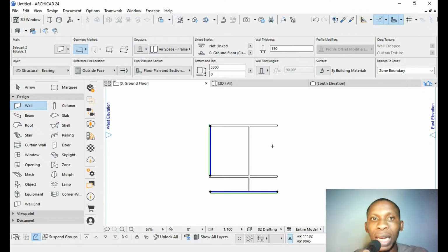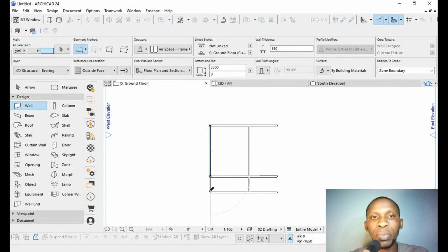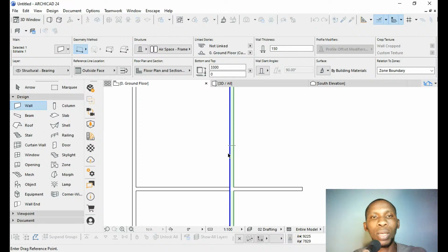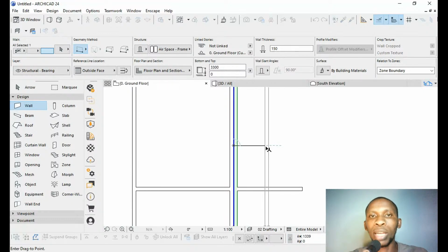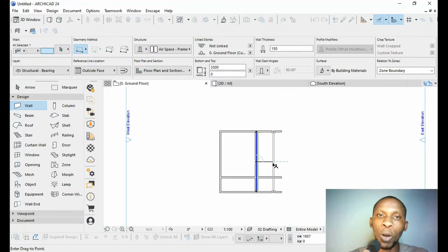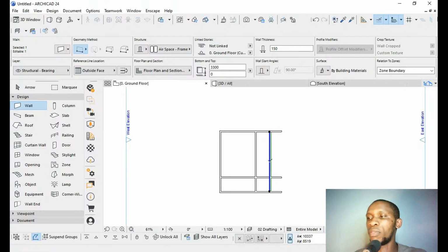The next class we'll be having, right? So I'll drag this down and click together, right? So it's connected. What I'll do now is drag this out, Control D, drag a copy, and then Control again, drag copy. So I will now click 150, and I click Control D. This time I want to drag just that particular copy, not dragging a copy. So let's use 1.5, 1500 millimeter space here. Click on Enter. Right, so I have this as my space example.